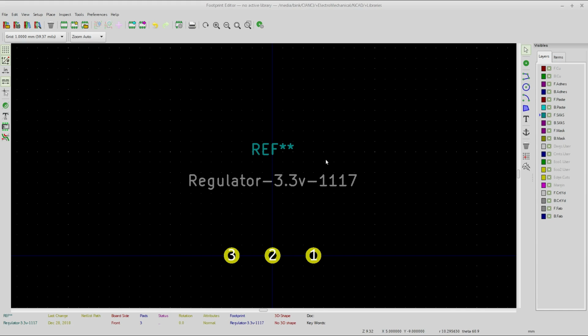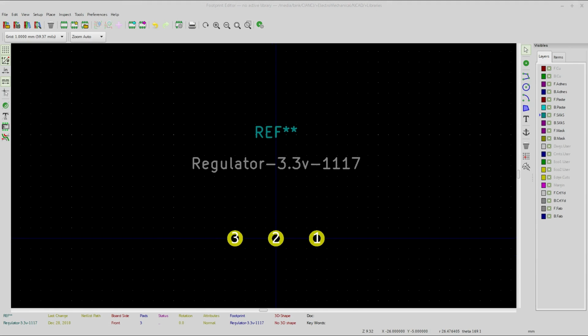And the box, again, it's a graphic, but it's an indicator to us on the PCB to not place anything else there because we're going to lay this component on it. Okay, so we need to get some specifics. We need some hole sizes, and after we get the hole size, we can come up with the diameter. The yellow part here is actually the copper that you're going to solder to. So you can almost make it as big or small as you want.